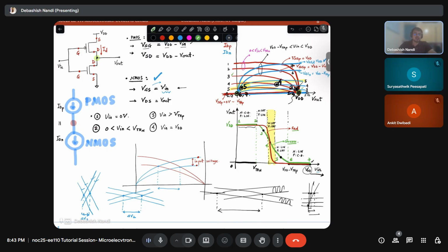The red one and the green one. Which one is better for an amplifier application? For CMOS inverter or switch applications, we know that the red one is better, right? Because the noise margins will be sufficient, or better, in case of the red one. But what about amplification?